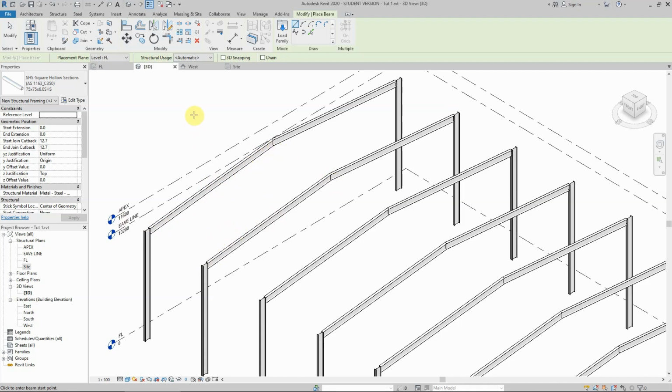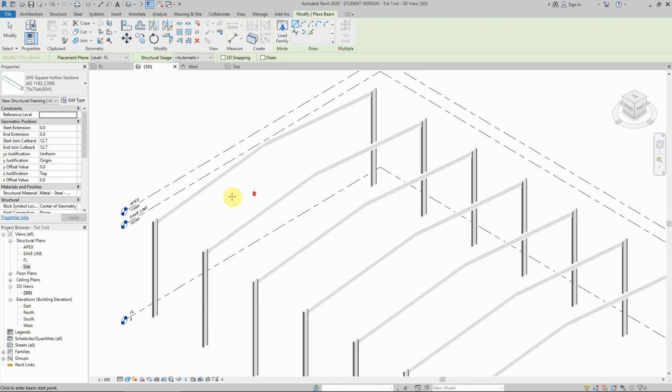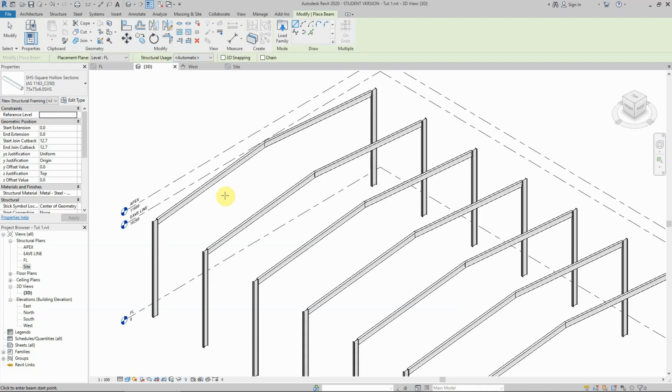Now, to start with, if I draw my strut from this point to that point, first of all, I can't click. If you get to a point that you are drawing in 3D, which is the way we place bracing and struts in 3D easier, I can't select where I'm connecting to. That's because your 3D snap is not checked, so just tick the box for 3D snapping. Now, as you can see, I can select the midpoint of these two rafters. I can connect between them, but still, let's try to draw it anyway. We placed our strut here.